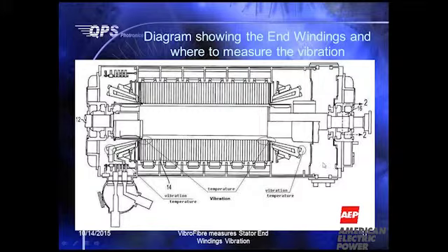It was pointed out that the resonance frequency of the end winding structure depends on temperature. The temperature of the generator may be operating all the way up to 85 to 100 degrees. So sometimes people measure on the bump test at room temperature and get a value, but in operation, this resonance might go down by 10 to 20 hertz. So this is something that we should pay attention to.